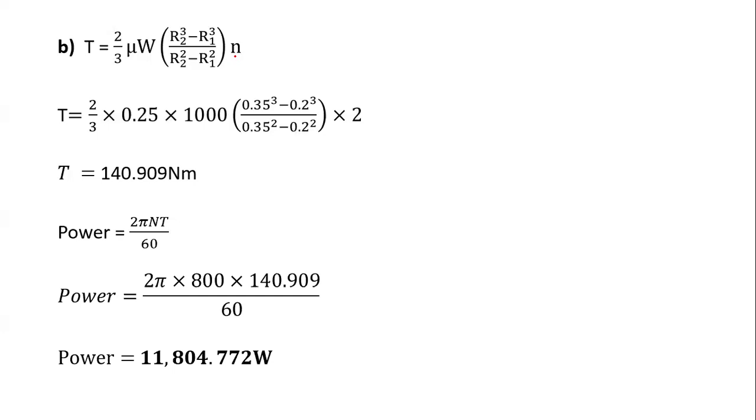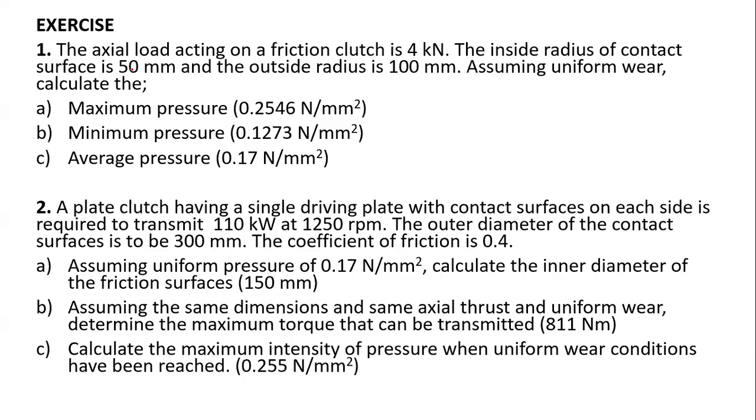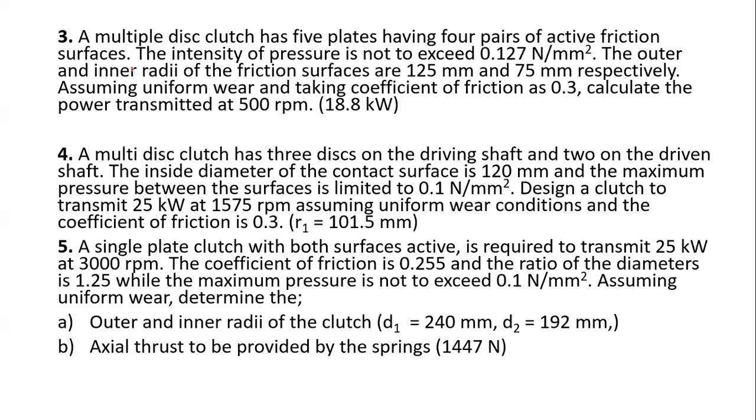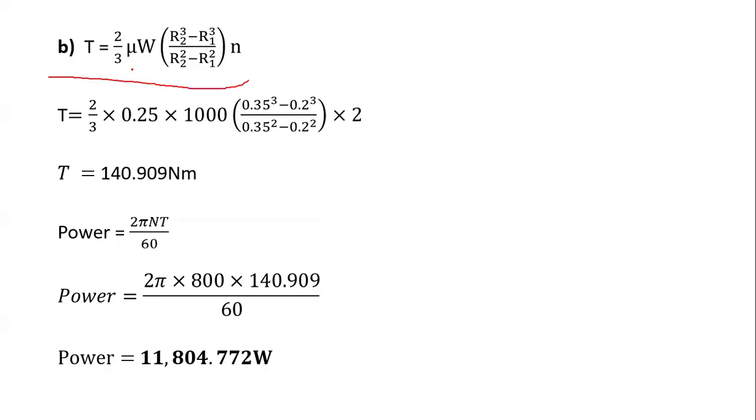Now, it doesn't matter whether we've been required to find the radius or the spring force. You basically use the same expressions we've discussed here and transpose what you're looking for. Is it the number of surfaces you're looking for? Is it the coefficient of friction? You make it the subject and you get your answer. So see how you do that in this exercise, and feel free to let me know when you need to reach out.